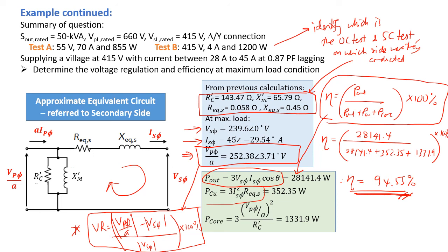So please make sure you're aware that in the three-phase transformer, for the power calculations, there must be a 3 in front, and you must use phase voltages and phase currents in the equations. So please study this example for your preparations for the final exam.